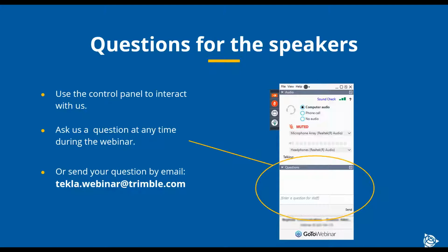Hi, Philip. Yes, general ECFs will be provided within the software so that you can get an immediate calculation for your carbon for the structure that you have created. But more detailed ECFs will be provided by the manufacturers of the elements that you are wanting to use in the modeling of your structure. So that will be a great place to start. You have full control over which elements are associated with which embedded carbon factors.